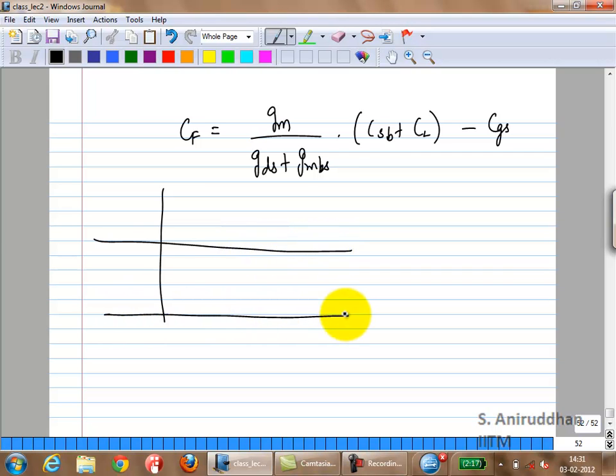Okay? So what you would have had earlier is, let me do a better job with this. With the earlier one, you started off somewhere close to 0 dB, which is 1. Correct? So you had one pole and one zero, right?